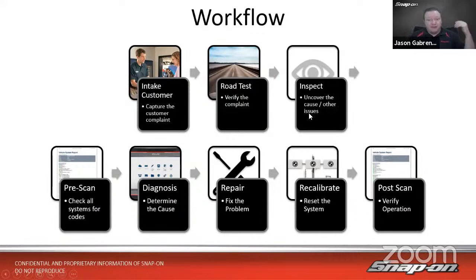And then inspect. Put the vehicle up on the lift, inspect it. Go do that 4-corner check on the vehicle, check the tires, check the wheel bearings and all that. Just to uncover the cause possibly, depending on what it is. And then, of course, uncover other possible issues with the vehicle as well.